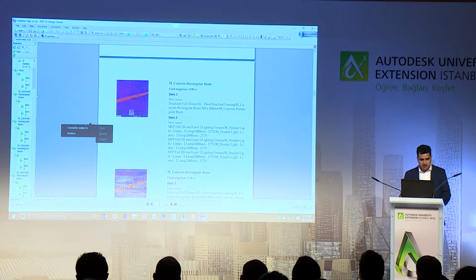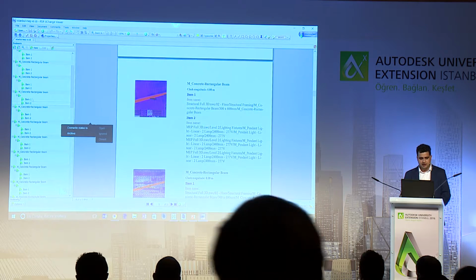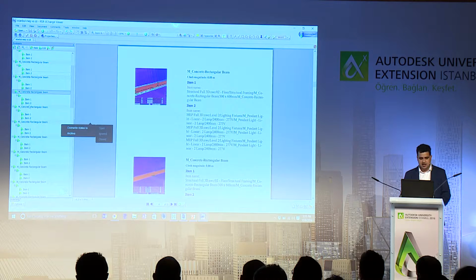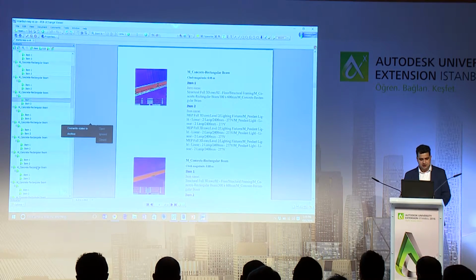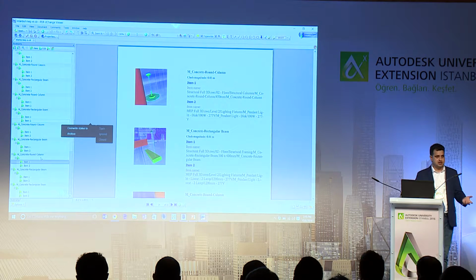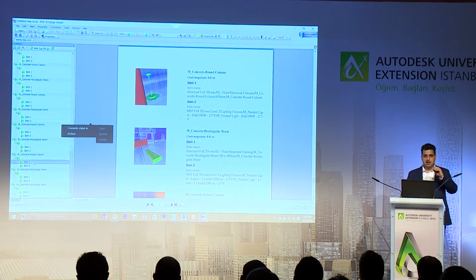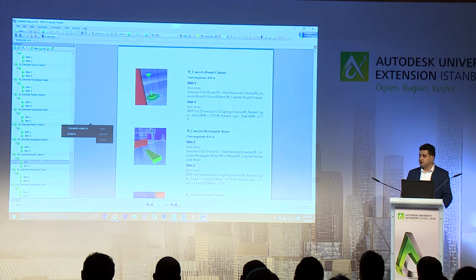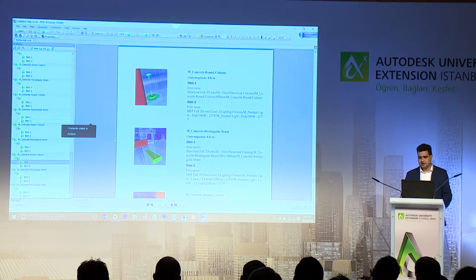So you can look at these clashes one by one. You can see that there's this clash. It has item 1 and item 2 clash. You can simply look at those beams and all that. This is for documentation purposes, because you might want to capture that weekly or bi-weekly clash report. So you can have those clash reports generated, and they will be available for future reference.